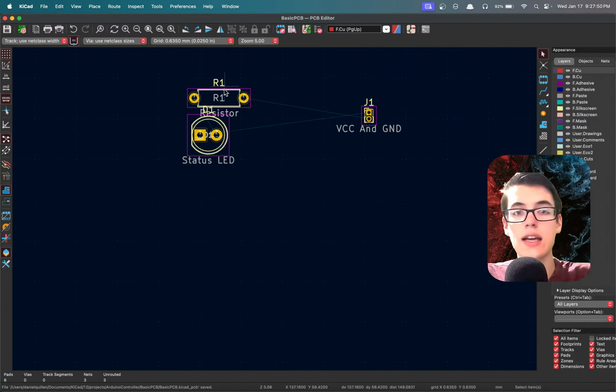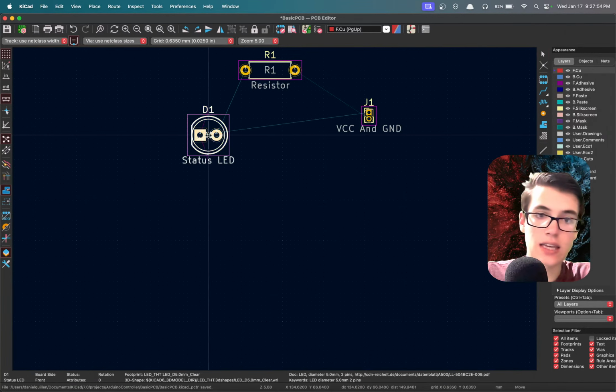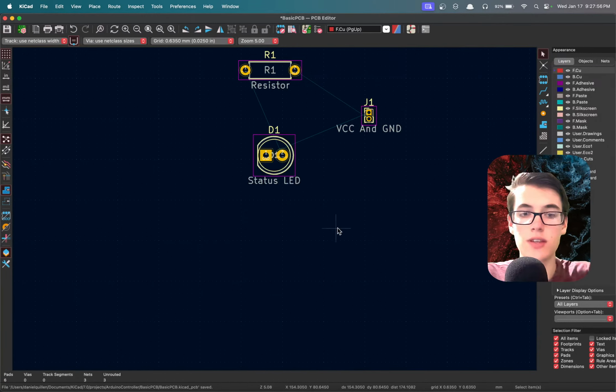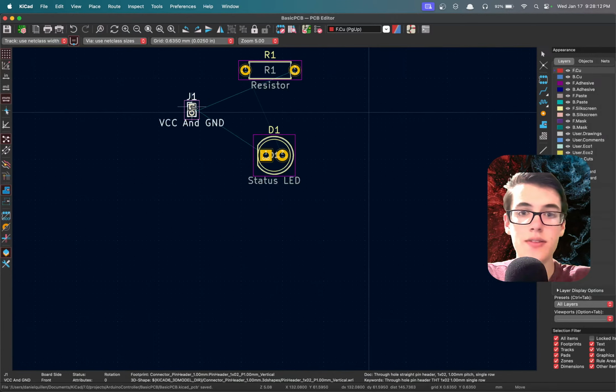And you can see what KiCad has done for us is, once again, hovering over something and pressing M allows you to just kind of grab it and move it, and it'll bring along all these little letters and stuff that go with it. It'll draw these faint lines to let you know where your connections are supposed to happen. So you can kind of position your components roughly where you want them to be.